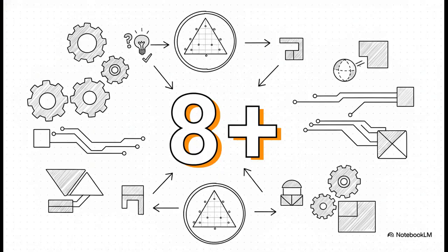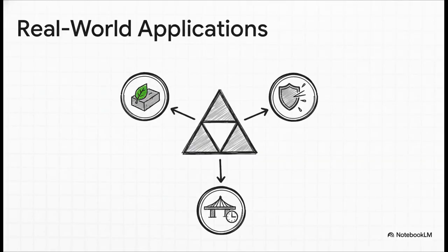These maps are the key to helping engineers finally manage the incredibly complex dance between all those 8+ chemicals we saw earlier. It lets us move past trial and error and start intentionally designing better, more reliable materials from the ground up. With these maps, we can actually engineer concrete to face specific challenges. We can design more sustainable cements that use less energy to make, which is great for our carbon footprint. We can also predict and stop harmful chemical attacks from stuff like de-icing salts or sulfates in the soil, making our roads and bridges last for decades longer.